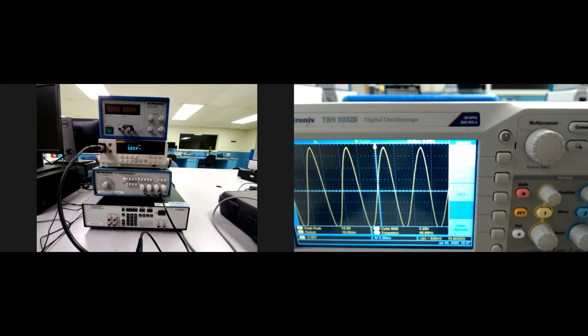Okay, if we are ready to go, Ryan, this last step for assignment 2, please, if you can help us. Set the function generator output frequency to 10,000 hertz. Record the voltage peak to peak, the voltage peak, the voltage RMS, and the period. Thank you. So here, we're gonna keep the same amplitude from before, those 5 volts RMS.